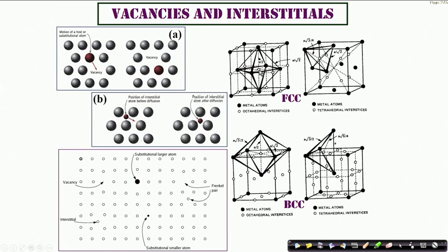Since this vacancy is surrounded by 6 atoms, you can imagine this central position as surrounded by 8 faces of triangular shape, and hence you call this an octahedral void. So an octahedral void will be coordinated by 6 atoms and 8 surfaces.